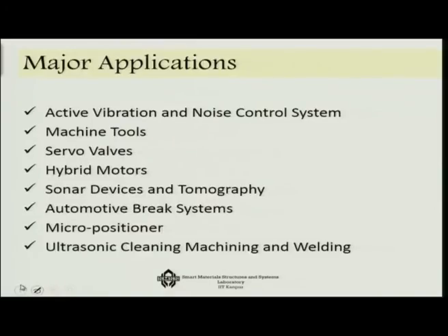What are the major applications? We can use this material for active vibration and noise control systems, for machine tools, for servo valves, hybrid motors, for sonar devices and tomography, automotive brake systems, micro positioning, and ultrasonic cleaning, for machining and welding. So there are varied applications in which you can use it. The initial application was in terms of sonar devices, but now you see there are so many different applications of these magnetostrictive materials.